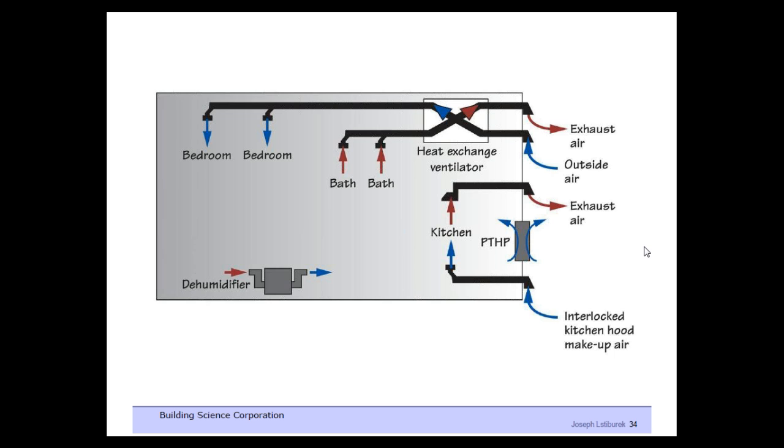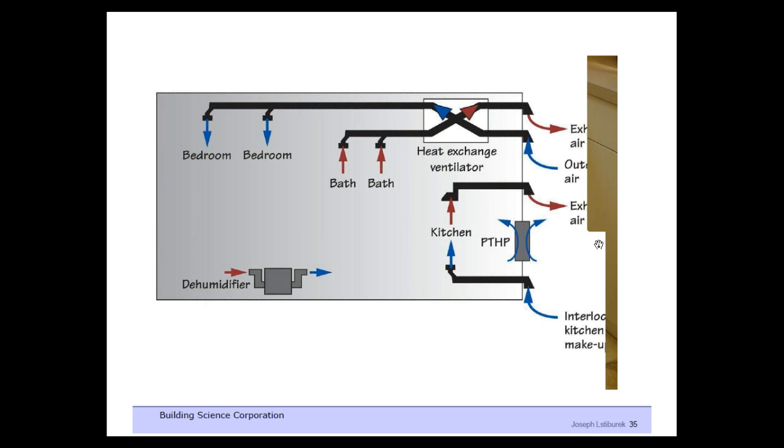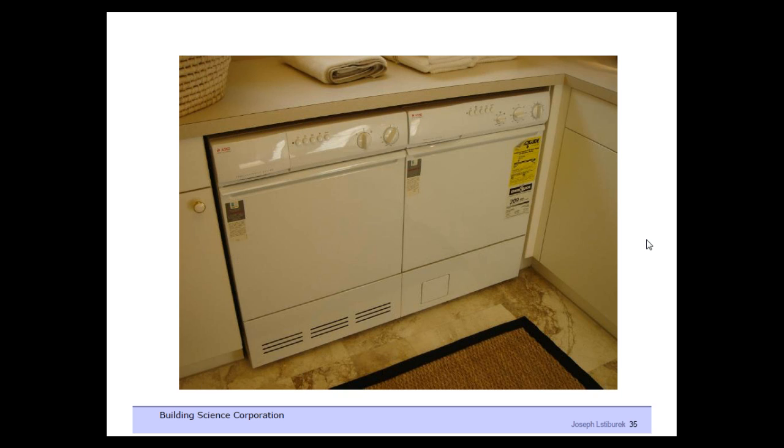We're going to just have to suck it up and accept that, or we're going to have to lower the rates. Good luck with that approach. Get used to condensing dryers. 200 CFM of exhaust from a standard dryer isn't in the cards anymore. And I have yet to see a practical makeup air system that's interlocked with a standard dryer.